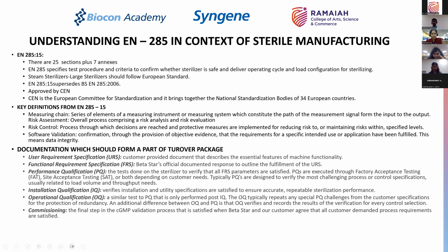PQ is a terminology used in 285 and covers the entire qualification process. But in a typical qualification process, the first thing that you do after the design qualification is completed is your factory acceptance test. So the vendor has built the equipment for you. You go to his factory and carry out certain tests on that equipment, including looking at whether he has constructed the equipment as per the approved PNID, whether it is as per the approved drawing of the equipment. You measure the dimensions to make sure that the dimensions are correct within a set tolerance.